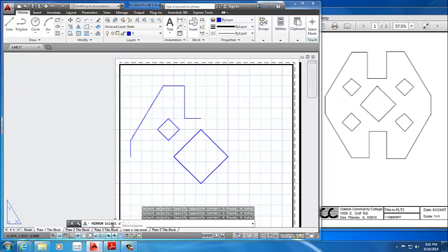You have to select the object first. Once you have selected, in the command bar, it keeps on asking you, do you want to select objects? It's asking if you want to select more. You can see it found 9 total already, which is right because that's what I counted. I need to mirror 9 objects. So now that's it. So what I type in is enter or space or right click enter. Do not escape. If you escape, you leave the command. If you click enter, you're moving forward with the command. So if it's asking you, do you want to select any more objects? No, I'm good. So you click enter. No, that's it for now.